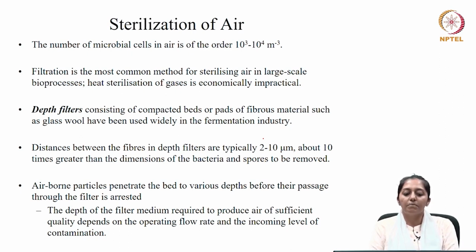Now the distances between the fibers in depth filters are typically in the range of 2 to 10 microns and about 10 times greater than the dimensions of the bacteria or the spores which are required to be removed. So it's very interesting to note that this kind of a setup is used to get rid of much smaller size bacteria present in the air.